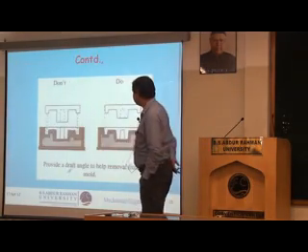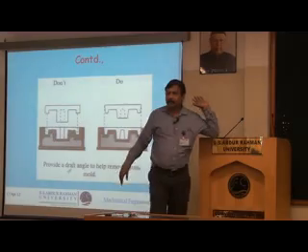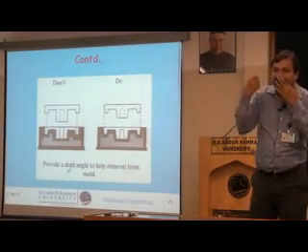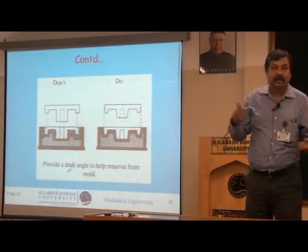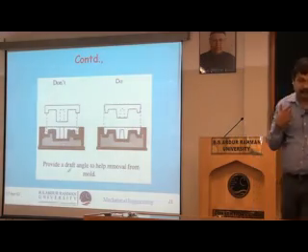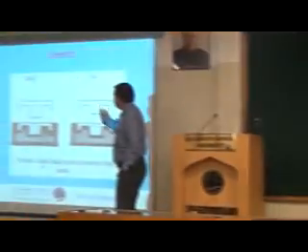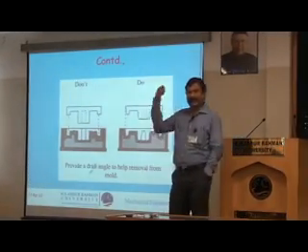Next slide please. Again, you have to provide a draft angle. Otherwise, you would have prepared the mold. After preparing the mold, the pattern is to be taken out. Have you prepared the molds? Yes, sir. In your lab, you would have prepared molds, isn't it? After preparing the mold, the pattern is to be taken out, because in the place of the pattern only you are going to pour the molten metal. So how will you take out if you don't have the draft? This angle is called the draft. So liberal draft must be provided so that you can take out the pattern.